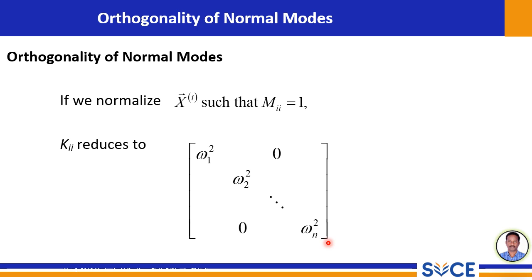This further emphasizes the independence of the normal modes. In essence, by appropriately scaling our mode shapes, we can represent the system's stiffness property in a very straightforward manner, directly linked to the system's natural frequencies. This simplification is highly beneficial in advanced vibration analysis and control applications.